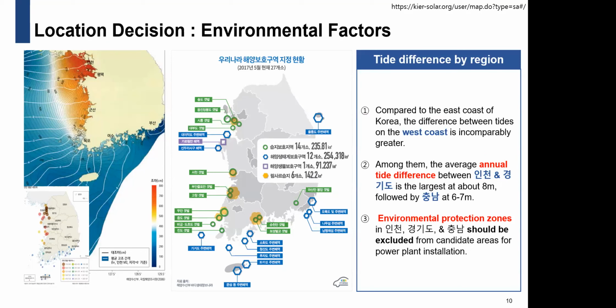Can I see the map? Oh, here it is, Uldolmok. Uldolmok is between an island and the mainland, so the flow should pass between them, and there is a very high speed tidal flow. Open channel should be located around that kind of Uldolmok, not toward the mainland side. Between land and island or strait, sometimes there is a very high flow, twice per day. Uldolmok is a very typical case. So you need to check the statistics of current speed there.